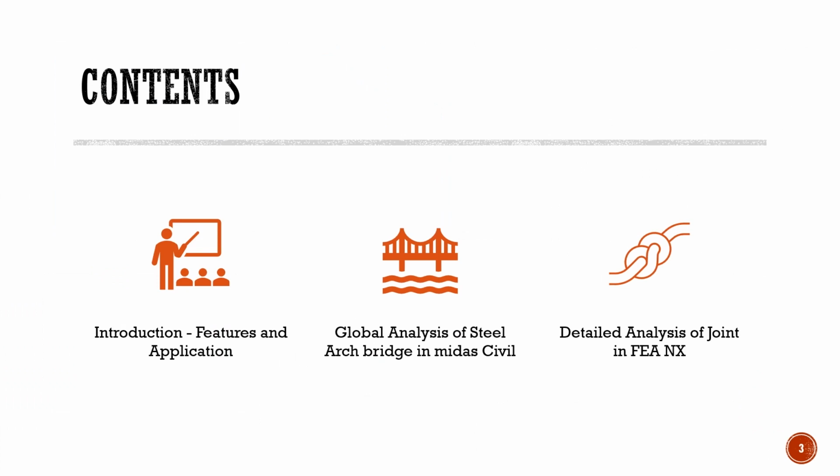In today's webinar, first we'll discuss various features and applications of MIDAS Civil and MIDAS FE NX pertaining to the modeling and design of steel bridges. Then we'll consider an example of a steel arch bridge and cover everything from the modeling to the design. In the later part of the webinar, we'll consider a steel joint in FEA NX, model it using the tools available in FEA NX, and perform the detailed joint analysis.